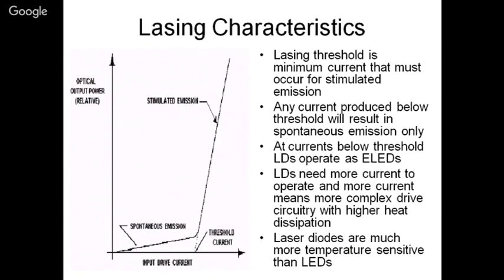That is the minimum current we have here. Here only the laser will lase. When you give this much current, then only lasing action will take place. Otherwise, till that time, what you have is an LED. And when the laser goes bad also, you are able to see a very dim light, which is something like an LED. Because otherwise, a laser you cannot see.